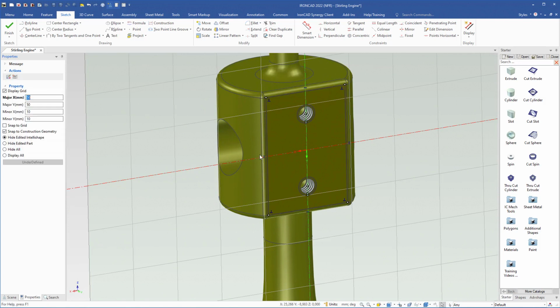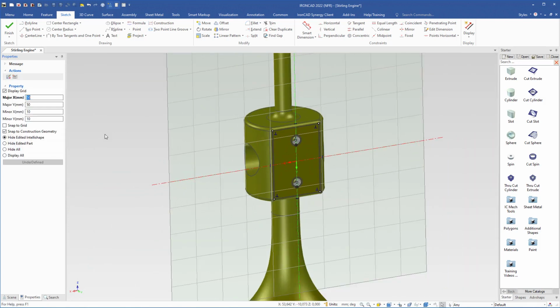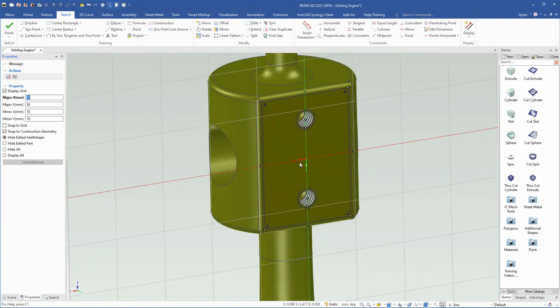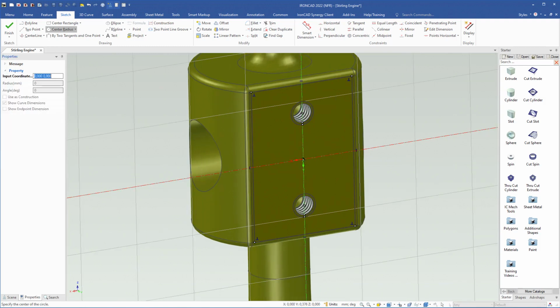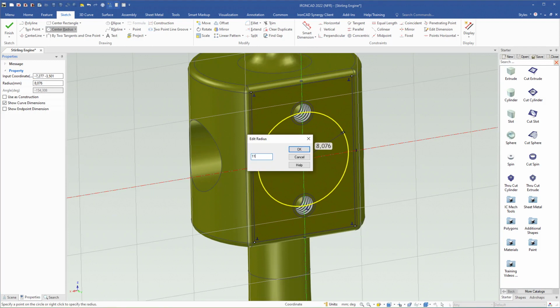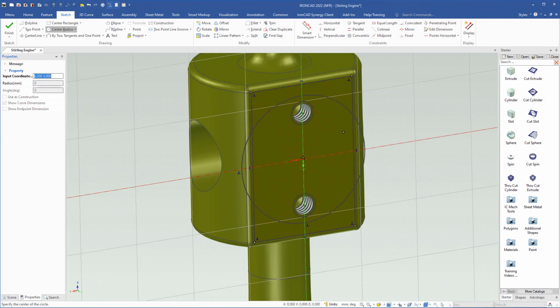The next step is to make the head of the bracket that will be placed out here. So we will use a circle to do that. I will press S and select circle, and I will click here on the origin. Then I will drag and right click and type 11, hit enter. Then I press escape to exit the circle command.